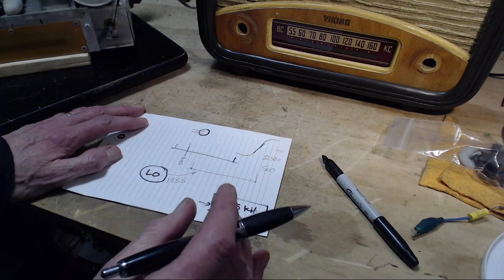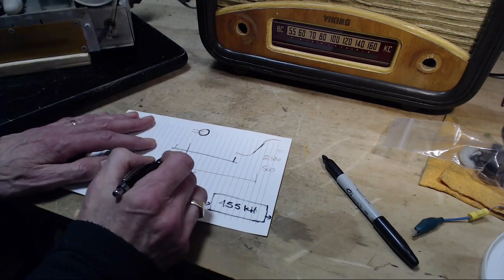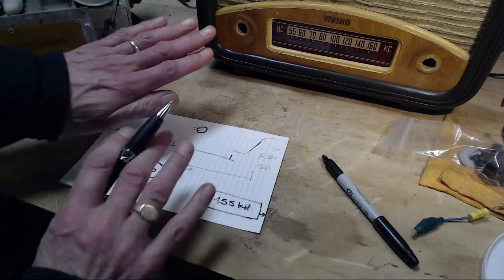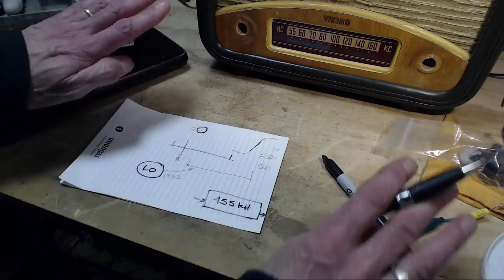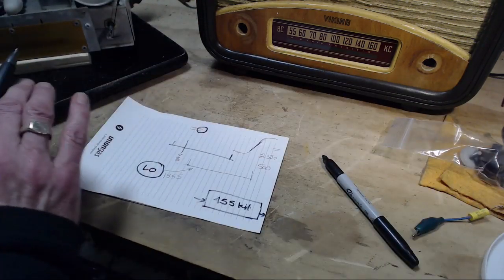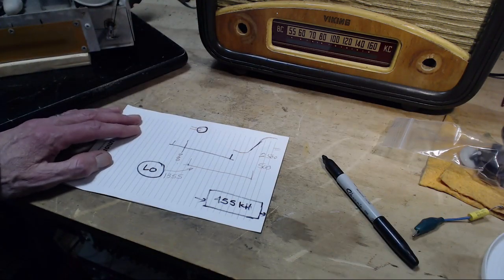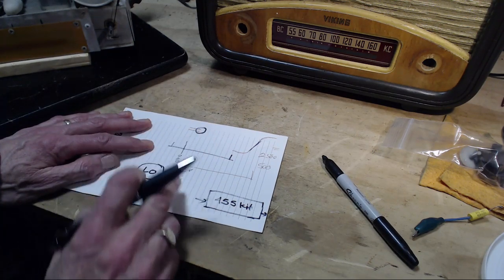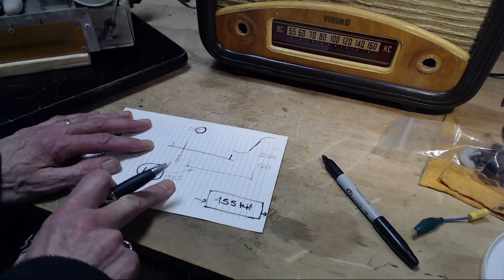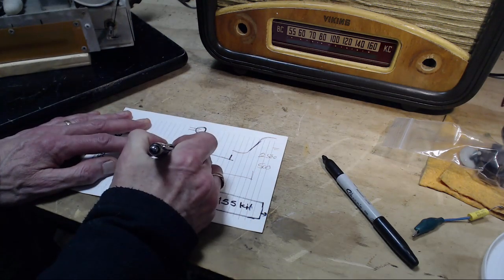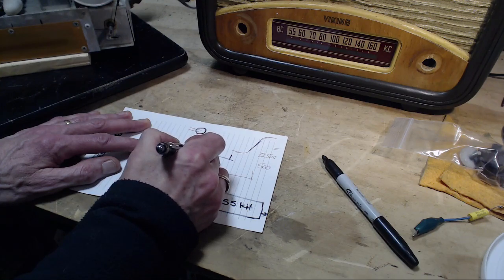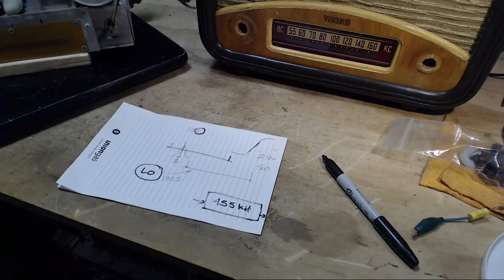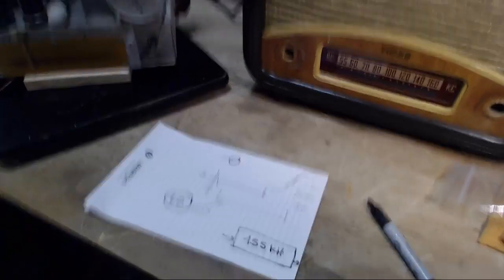So the radio tries to focus right in on the area of interest, and tries to push away everything else, or drop everything else, ignore everything else, or weaken everything else. So if you tune to 900, although you're actually tuning the local oscillator to 1355, part of the radio's tuning will be right here. This is what this whole thing is about.